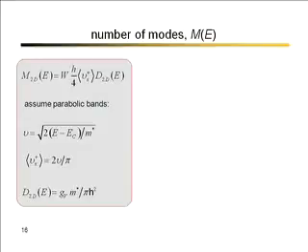Then the average velocity in the direction of transport, I'm calling it x, Professor Dada called it z, times the density of states. And these are two-dimensional electrons flowing in the channel, so I'm writing this as the two-dimensional density of states. Okay. I'm going to assume parabolic bands, just to make things easy. So the 1/2 mv squared is equal to the kinetic energy. So we can easily express the ballistic velocity in terms of the kinetic energy and the effective mass.